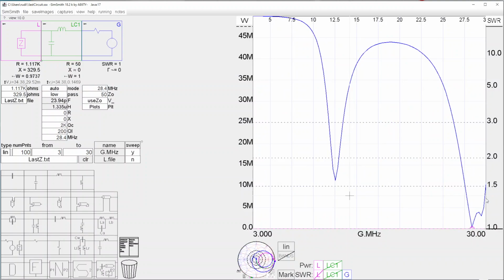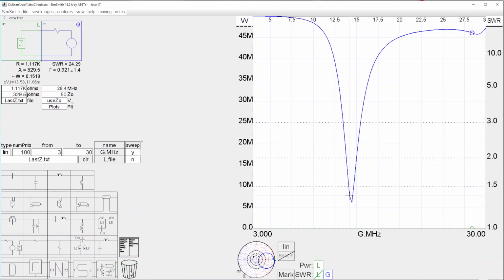So as a naturally resonant antenna, they tend to give you a lot more tunability with an auto tuner, which is a pretty nice thing. We could have retuned this, sure, and you saw how to do that with the off-center fed and the end fed. But with the vertical, an auto tuner up at the antenna at the feed point is a sweet solution. So let's get rid of this tuner, and let's now do our final example, shall we?